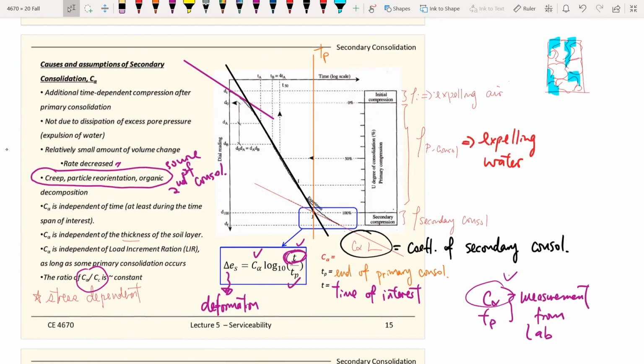Remember, our typical experimental data tell us the secondary consolidation deformations can be insignificant compared with primary consolidation. So for typical soils, or for a small-scale project like a building that doesn't have a very long design span, you maybe can get away with not looking into the secondary consolidation settlements.